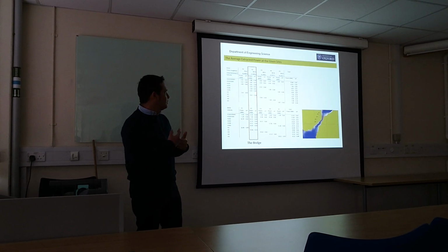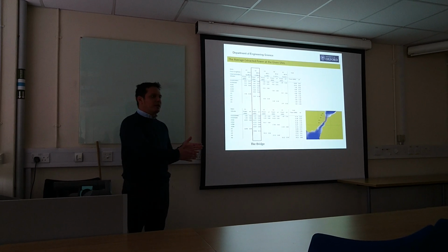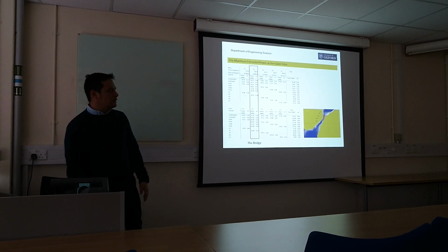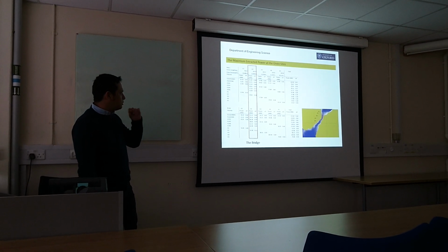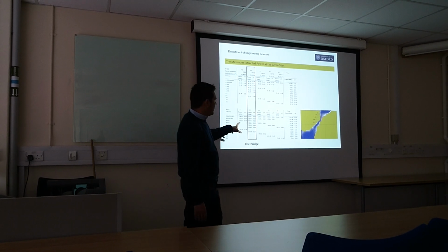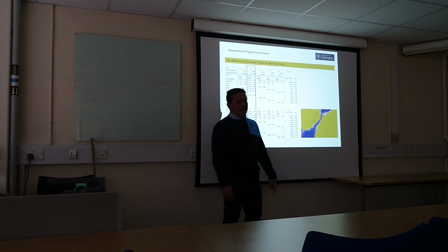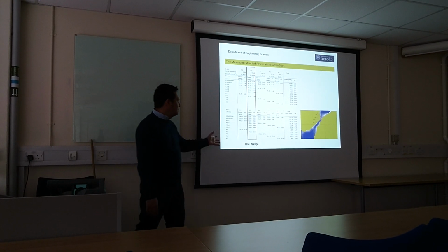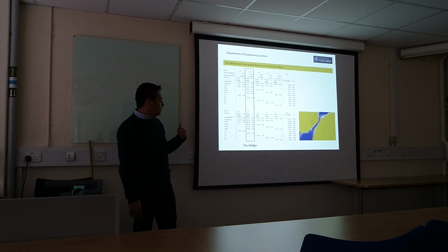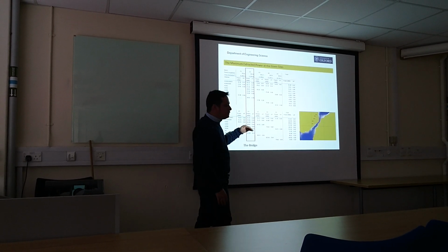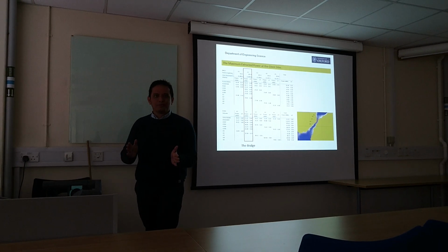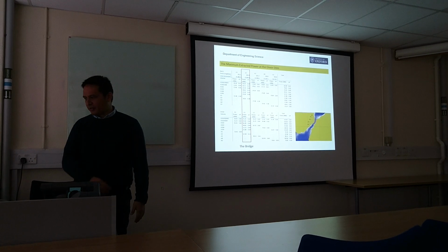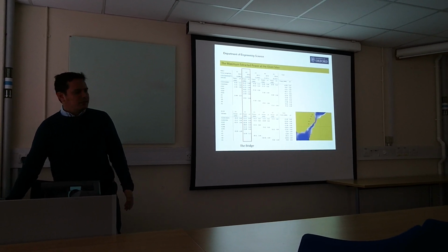So you can see this is even less than when you increase the blockage ratio at only one site. The flow is reduced when you put too many arrays in rows like that. And this is the maximum site power output of the turbines. You can see maybe some areas can reach more than 150 megawatts, but it has to be at a higher blockage ratio. It also has to be for more than three different arrays along the strait. But there are consequences like this.